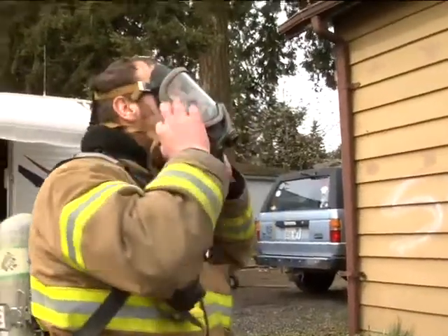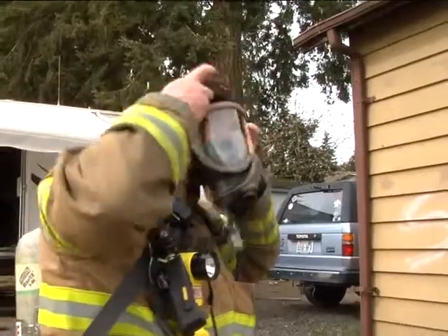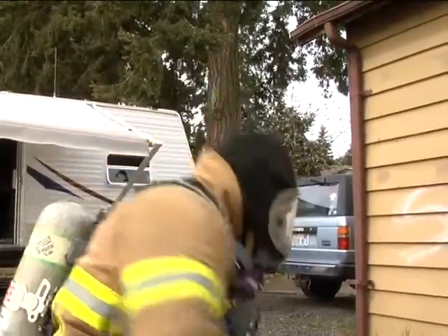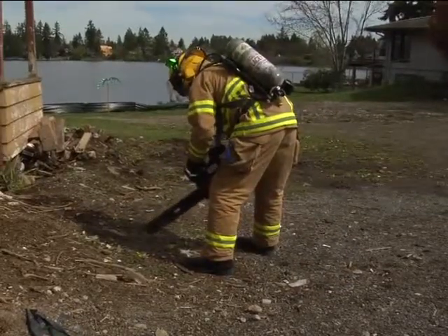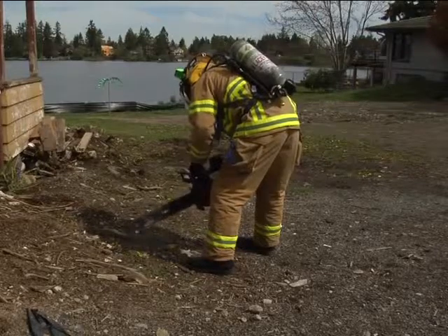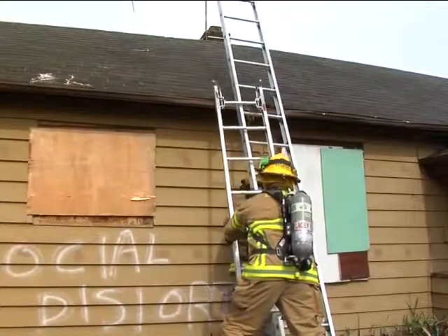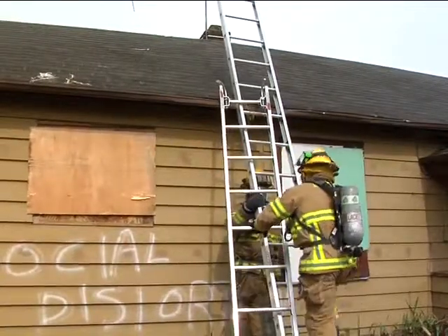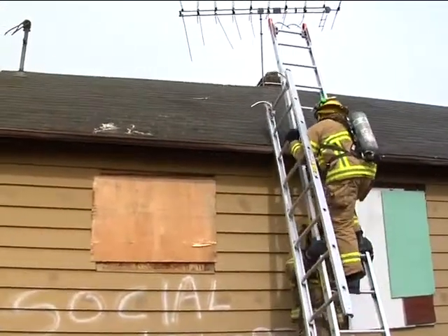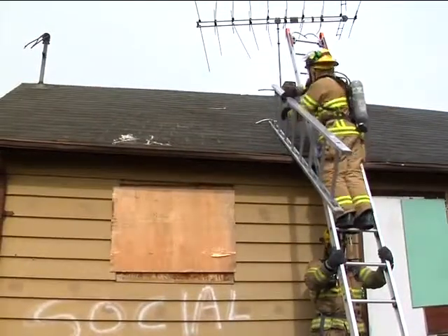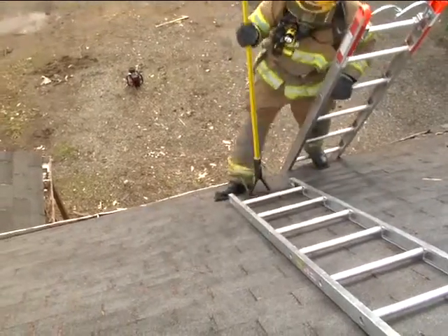If assigned to the roof, observe these general safety precautions. Always wear full personal protective clothing and equipment, including SCBA. Start power tools on the ground to be sure they are working properly, but turn them off when transporting them up to the roof. Work in teams of at least 2, but no more than the minimum number of people needed to get the job done. Extend ladders at least 5 rungs above the roof line. An elevated platform should be even with the roof line or slightly above it. Sound the roof for structural integrity before stepping out on it.